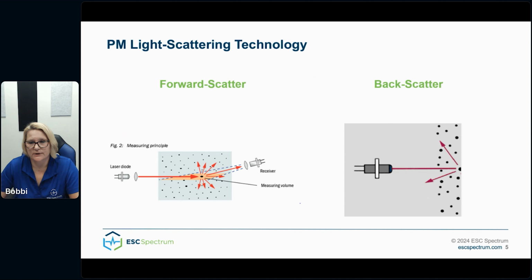As I mentioned earlier, PM CEMS do not measure PM directly. In light scattering PM CEMS, the monitor shines a light source into the flue gas sample and either looks at the light scattered forward or reflected backwards. The amount of light scattered is dependent upon the particle's physical properties and the concentration, which can then be mathematically correlated to a PM concentration under PS11.